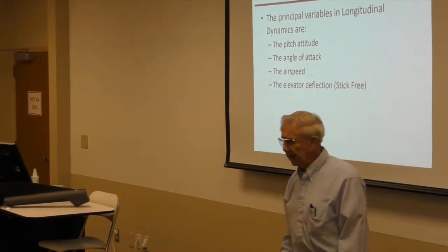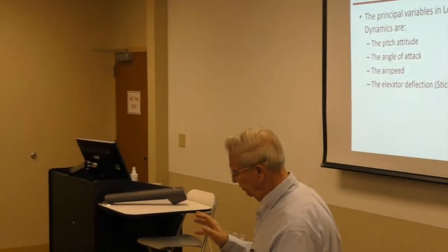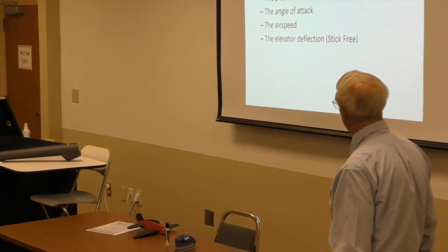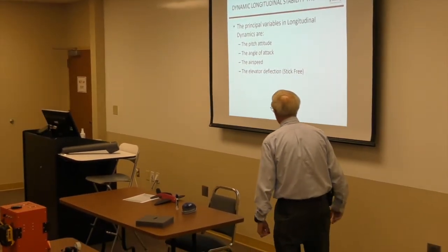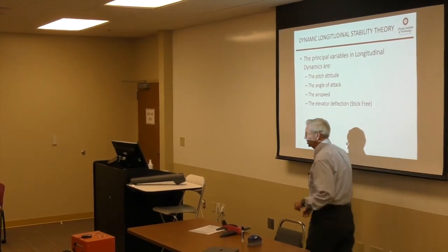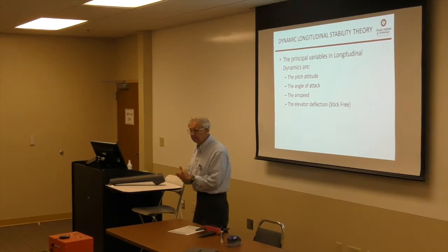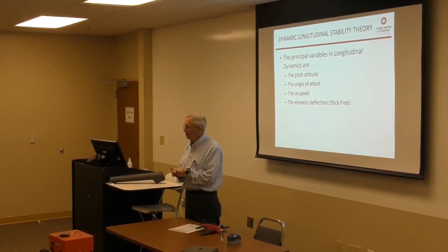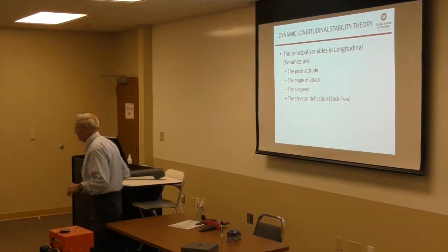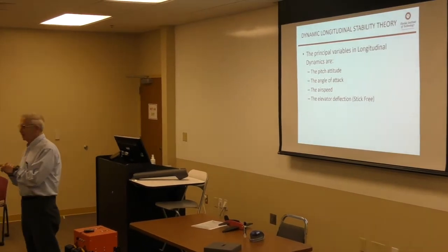Unfortunately, we don't have angle of attack in this box. I think you could probably deduce what it is, but we don't have it directly recorded. But we do record airspeed, we record pitch attitude, and we record elevator deflection. So you'll have all of those data. And you'll see the oscillation. Now, fortunately, or maybe unfortunately, depending on your outlook, the Cherokee 6 has oscillatory longitudinal dynamics, okay?